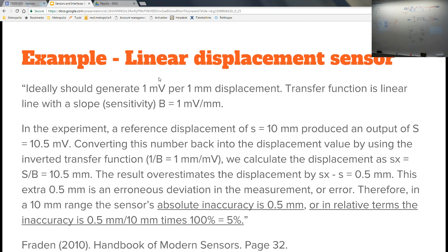It's basically just a variable resistor where this slide is the same as that button that goes up and down, and then at the one end you have the reference voltage, and on the other end you usually have the ground, and that one actually here gives the ratio of how much resistance you have here divided by total resistance times Vref.